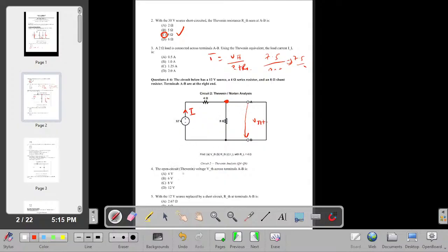So let's find the Thevenin voltage. We need the current I, only I. So I is equal to total voltage over total resistance, right? The reason we are finding I is that we want to use the voltage drop approach. Whenever they give you a very simple circuit, use the voltage drop approach. It's very fast. Please work with time. I is equal to the total voltage over the total resistance. My total voltage is 12 volts over my total resistance, which is 4 plus 8 because they are in series like this. So my current is simply 1 ampere.